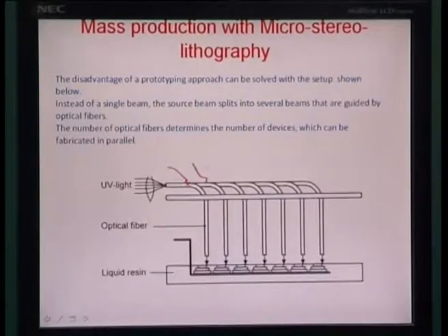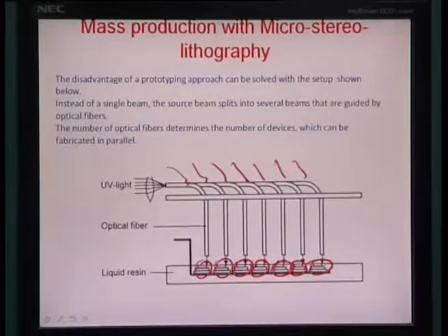So, people have used other methodologies, including some things like this, where you have multiple fibers, as you are seeing, which take the light onto different places where you can write all at a glance, all at once, and you can write many features in parallel instead of one.